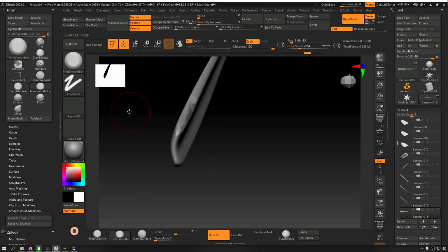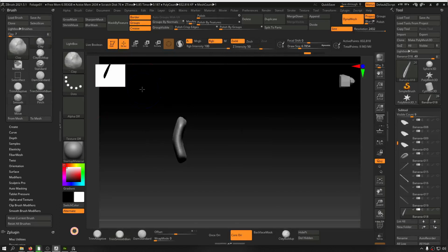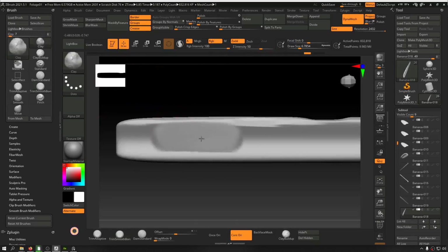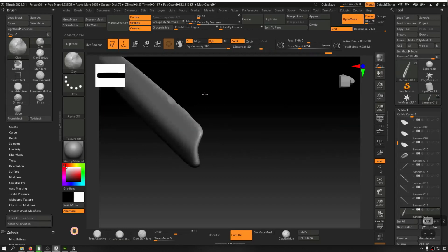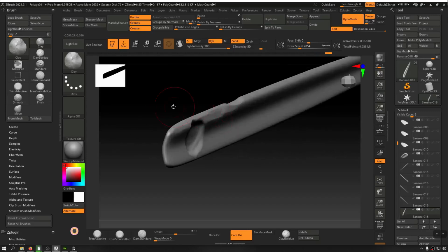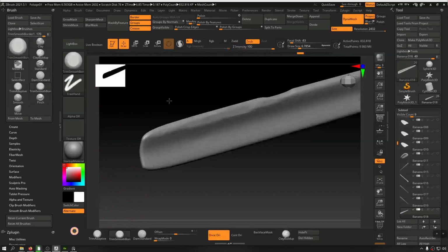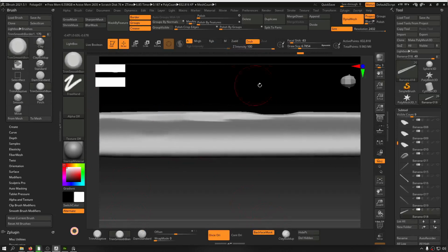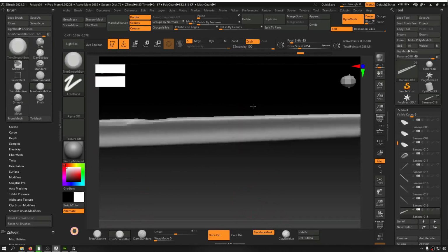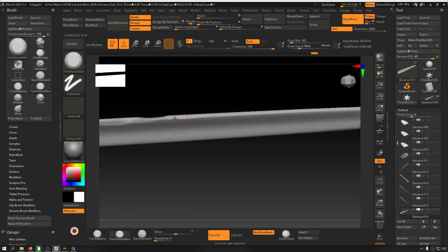If you try to add a lot of noises, of course using other brushes as well, or try to go crazy, it ruins that part as well. On these thin meshes, have the backface mask on. Okay, let's go for trim smooth border with the backface mask on. We have some edges to trim.